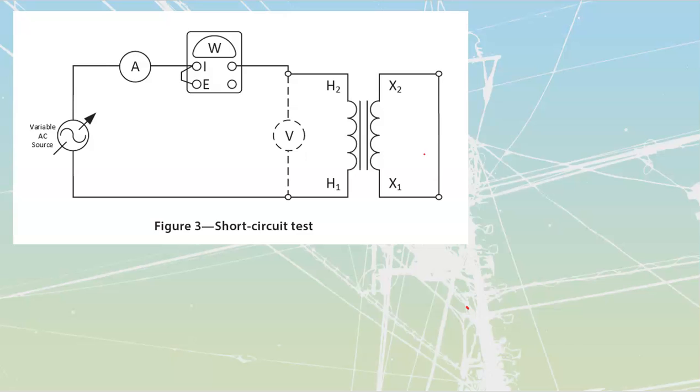If you go into your binder over there, they talked about the percent impedance voltage, or IZ, because IZ is the same as V, right? V is equal to I times R. What we determined off of this was our impedance voltage. Remember that? We said the VZ that we had. Now they're taking the V and expanding it into I and R, current and resistance. What's my resistance? Well, it's going to be an impedance. So instead of the impedance voltage, they call it the percent IZ. And then they divide out current to show that my percent V is going to be the same as my percent Z.